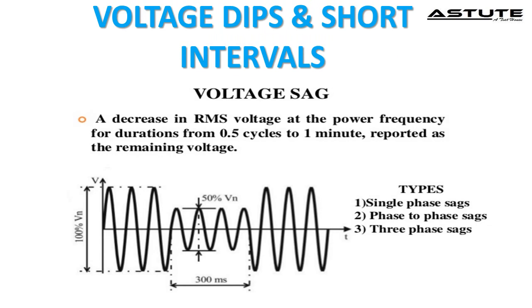Voltage dip is a drop in line voltage up to a certain level of AC mains voltage and is caused by faults in the network, in installations, or by a sudden large change of load. In certain cases, two or more consecutive dips or interruptions may occur. Electrical and electronic equipment may be affected by voltage dips, short interruptions, or voltage variations of power supply. In this test we can test the immunity of the device to the voltage dip.